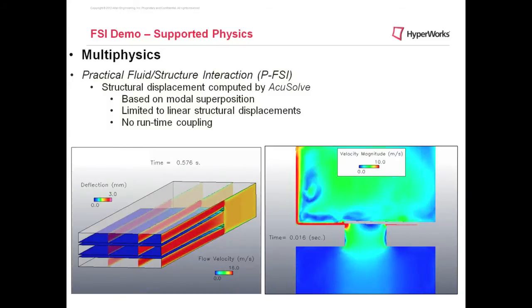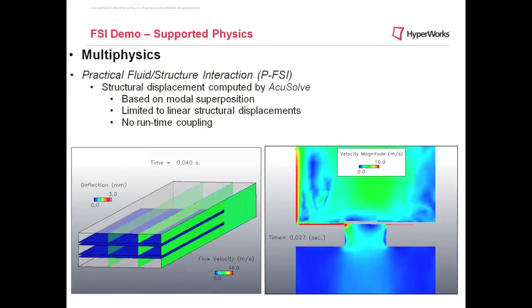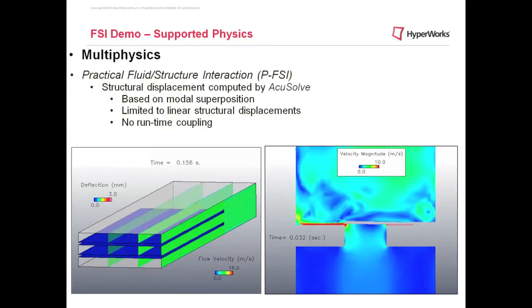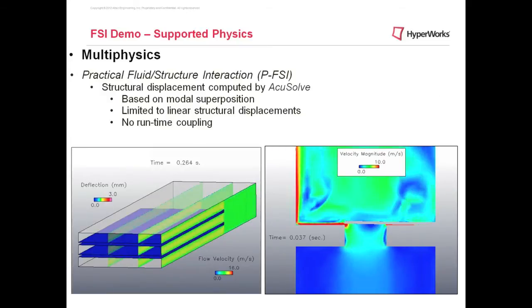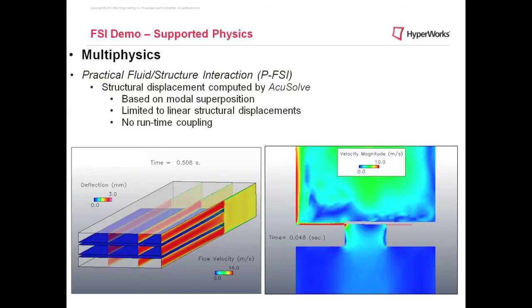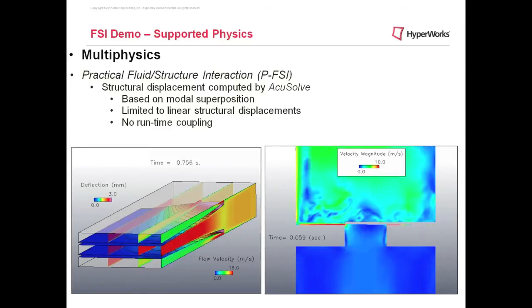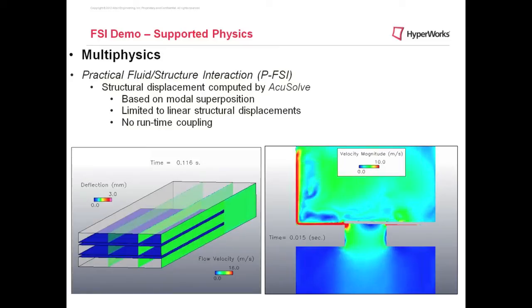The technology can certainly still be used as an exploratory technique, but we will introduce some errors into it. And the reason is because we're not reforming the stiffness matrix. The stiffness matrix is held constant throughout the simulation based on the original eigenvalues of the system.